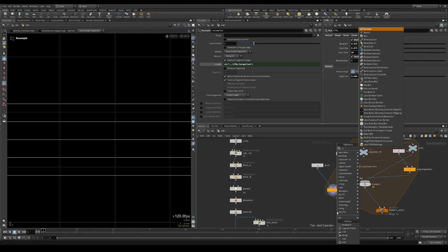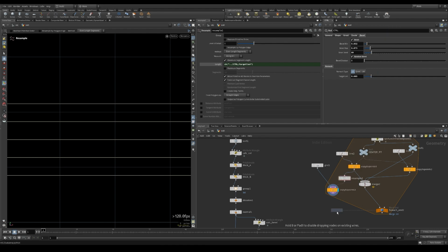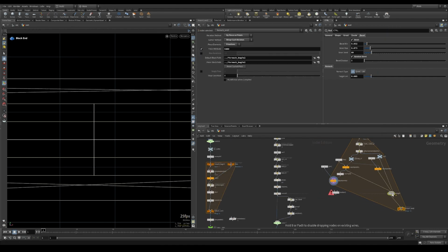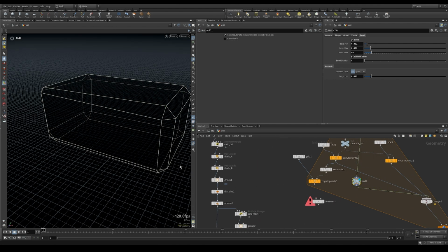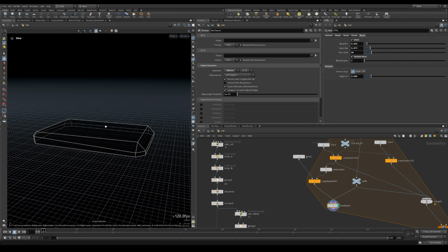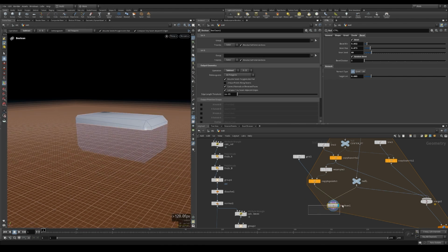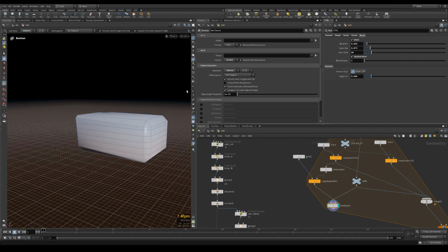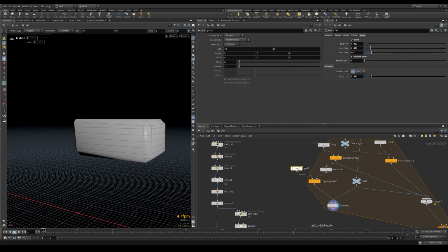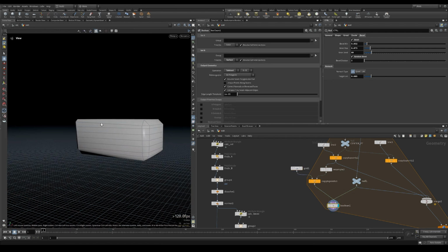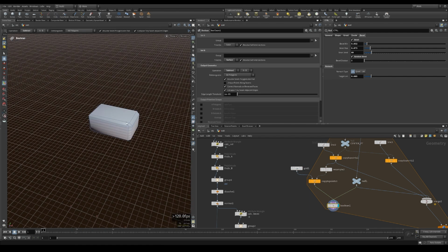So now we want to finally cut the brick. So take a boolean and let's make some room here. This is where the bricks are, and we want to cut from the brick to the line. And on the boolean, we need to say that set B is a surface, is not a solid. So we do have our geometry being cut. And just for safe measure, let's make this grid very big, so we are sure that it's cutting the brick no matter what.